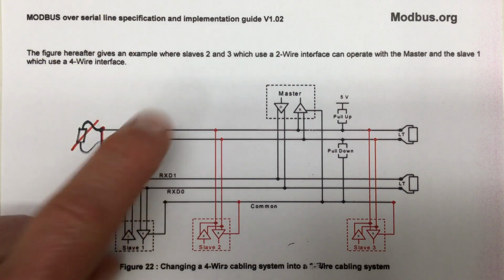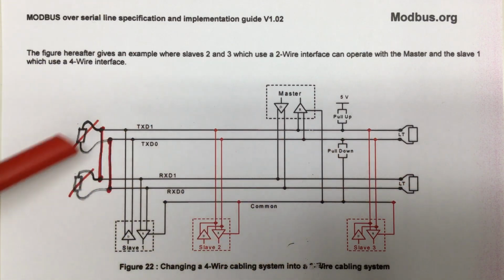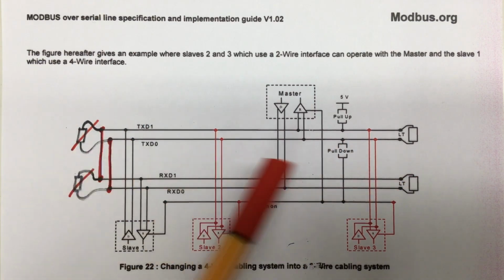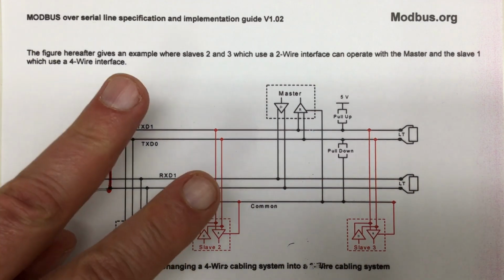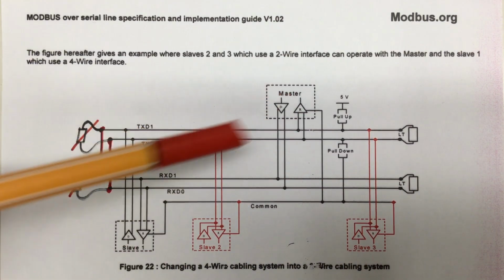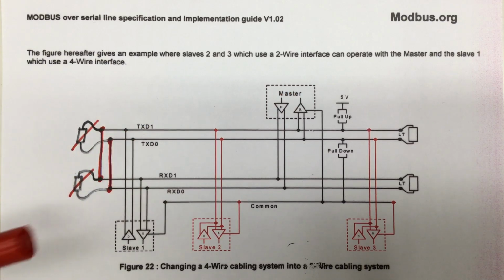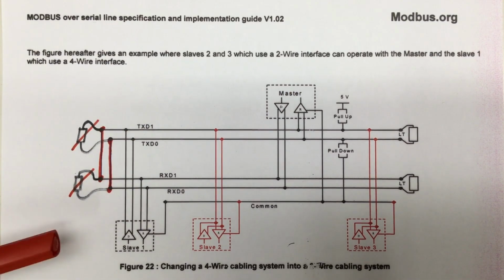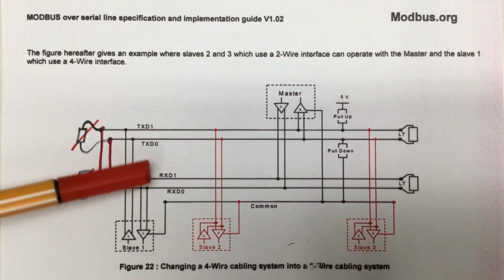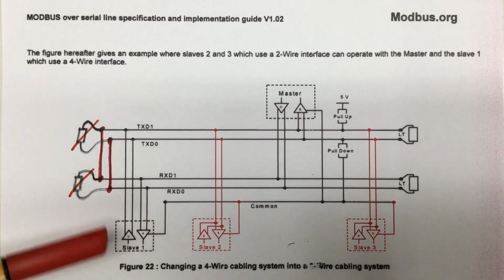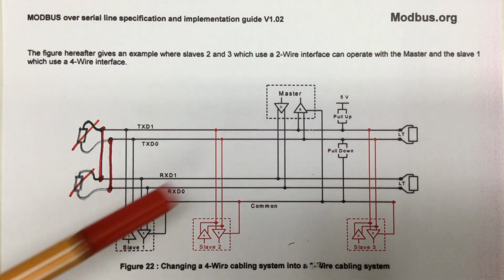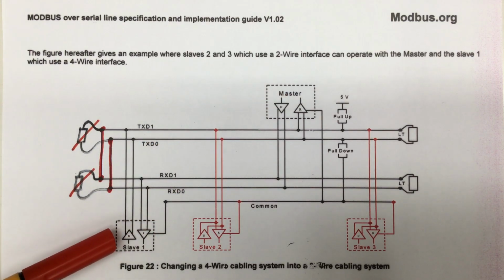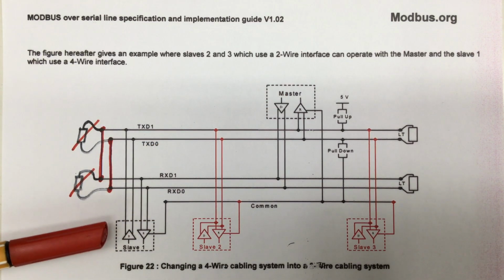Two notes here. First, we have now a transmission line that is twice as long as it needs to be. Second, our full duplex transceivers must be able to cope with the fact that they are now receiving their own transmission, either in software or by switching the read-enable pin of their receivers. Since they were designed for a full duplex system, that's not a given.